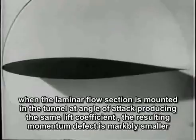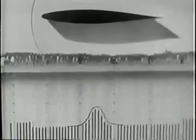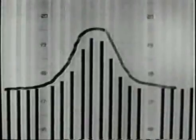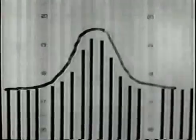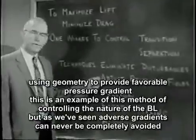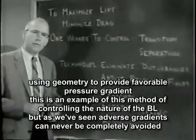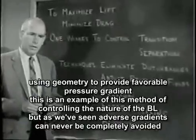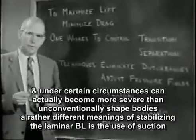When the laminar flow section is mounted in the tunnel at an angle of attack producing the same lift coefficient, the resulting momentum defect is markedly smaller. Using geometry to provide favorable pressure gradients is an example of this method of controlling the nature of the boundary layer. But as we've seen, adverse gradients can never be completely avoided, and under certain circumstances can actually become more severe than on conventionally shaped bodies.